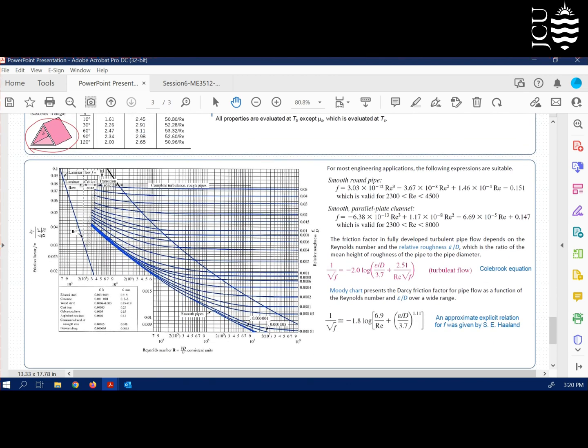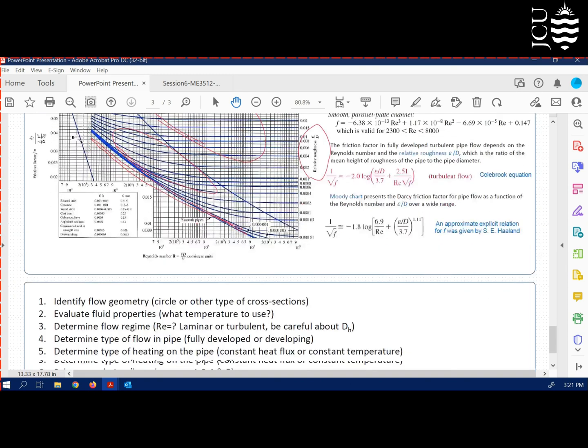And we talked about the Moody diagram, how it works. The x-axis was Reynolds number, the y-axis was friction factor, and the other y-axis was the relative roughness. And by increasing roughness, our friction is going to increase. And as you can see, we have 3 regions. The fully rough region, where the criterion for friction is mainly the relative roughness; the transition region, where we have the effect of both Reynolds number and relative roughness; and finally this region, where there is only the effect of Reynolds number and no effect of roughness. So if you are interested, again, you need to go back to the lecture notes and investigate a bit more the details about the Moody diagram.